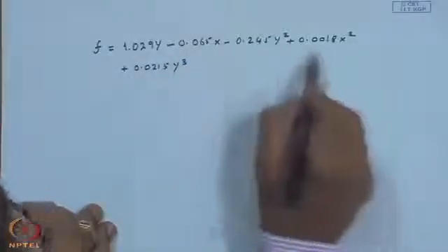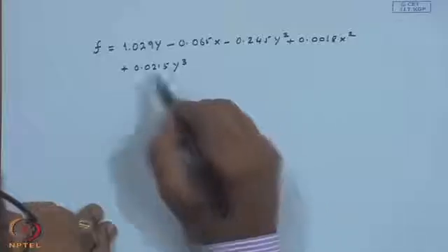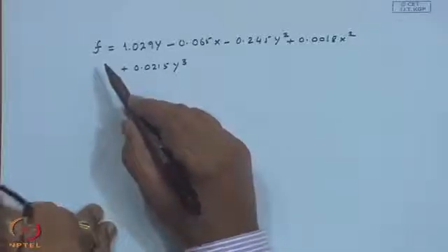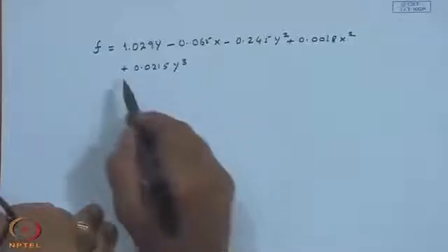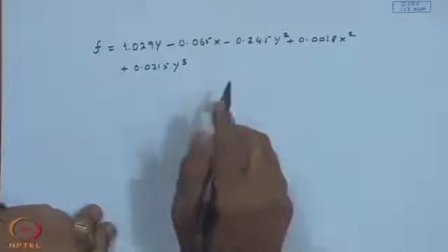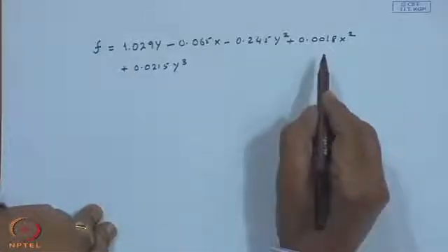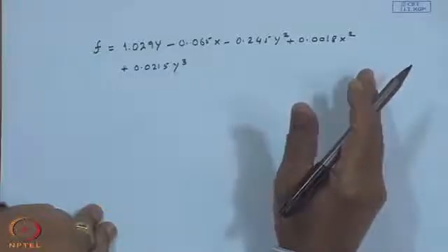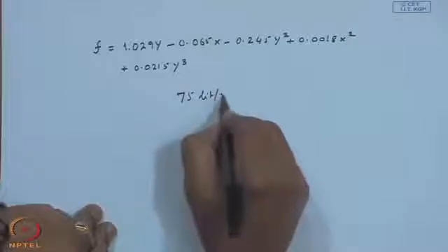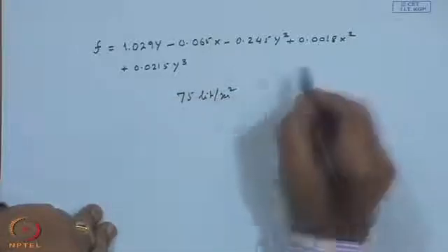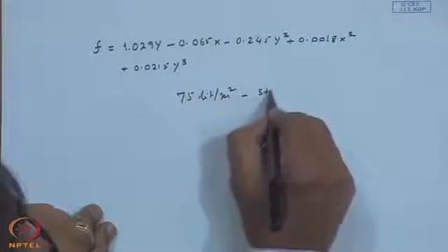However, the slight difference between air and liquid based systems comes mainly from the storage and the heat exchanger effect. In addition, the liquid based systems have a certain volume of water, like 75 liters per square meter of collector area, as the standard storage.